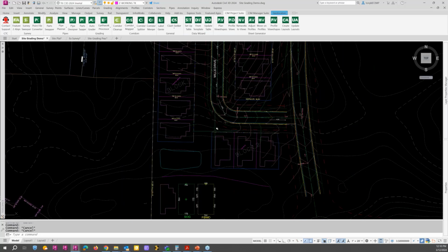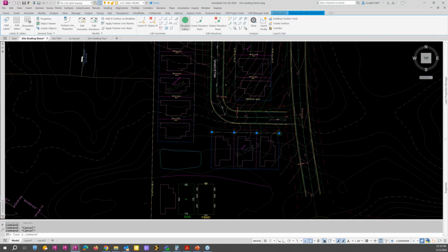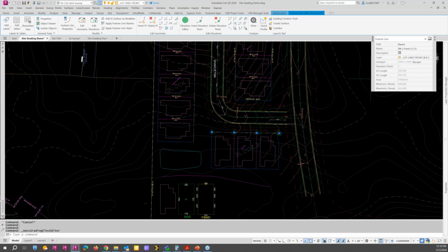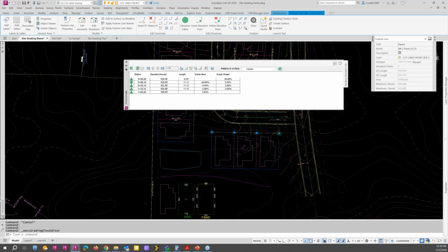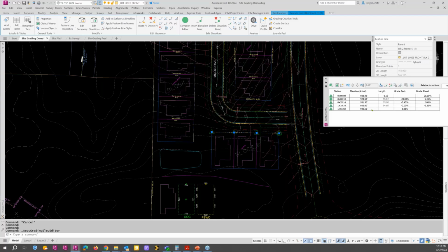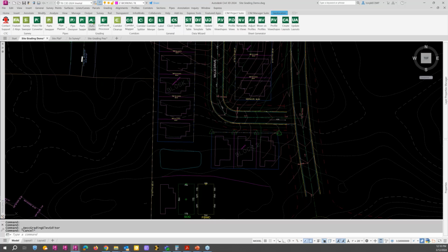So we're going to grade these. I created these feature lines, and I hope I didn't mess that up by copying over the top. But that looks okay. So I created my feature lines right there to go off of, and that's how AutoGrader works. Let's open up AutoGrader.